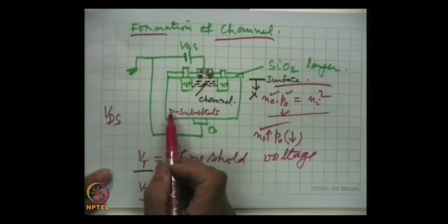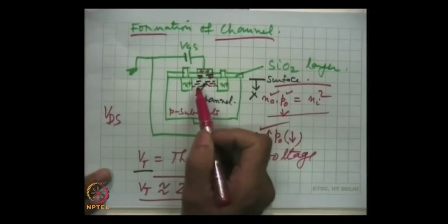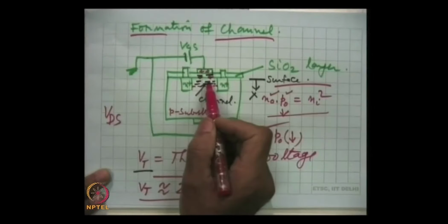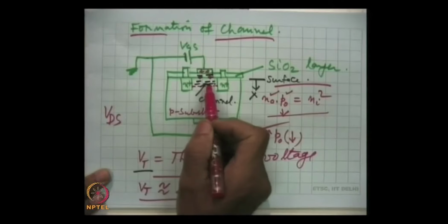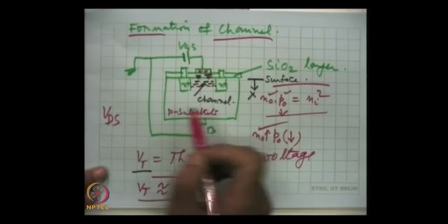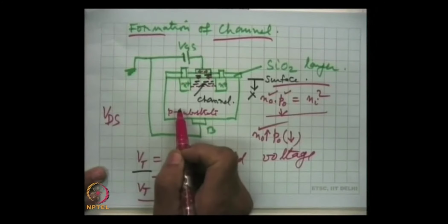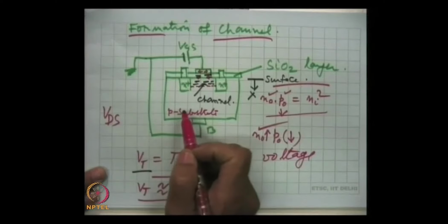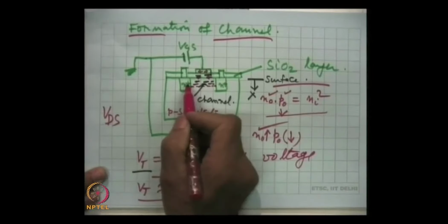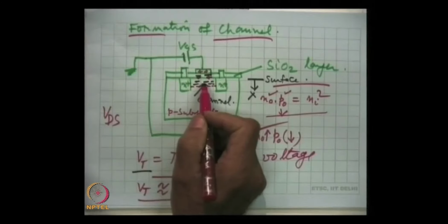this is the P-type substrate, there are plenty of holes, and in this P region there is now an excess of electrons. So, it is an inversion from majority hole density, a very important thing. Here in the P substrate holes are in the majority and electrons in the minority, but in the channel region the reverse has happened.